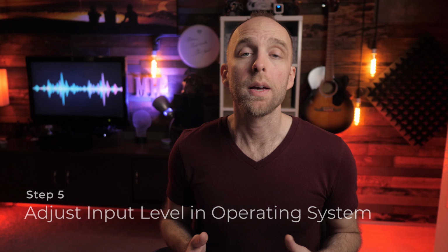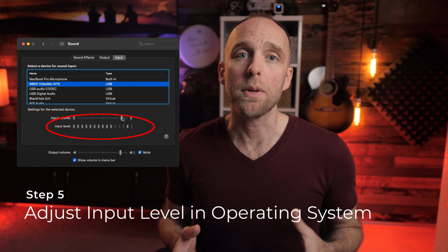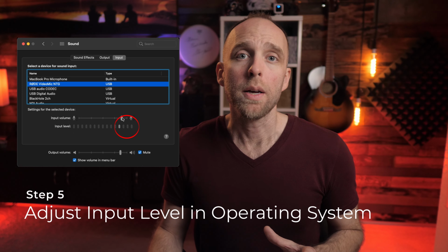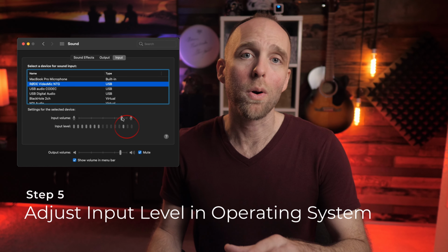All right, step 5, continue speaking and watch the input level here on your computer. So I can see the meters move here as I talk, and I can also see that we're almost clipping out. And many of you may reach for the gain knob on the back of the mic, but that will not work on this mic because again, when connected via USB, the knob on the back of the mic has no effect on the level into your computer.